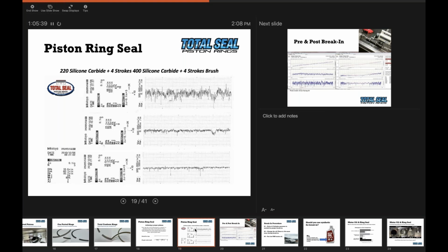Obviously, there's been some work done with dimpling and things at the very top near TDC to try to have a different texture in the area that needs it the most versus others, but I'd say for the most part, for bang for your buck and time invested, hone it the entire travel with the same finish.